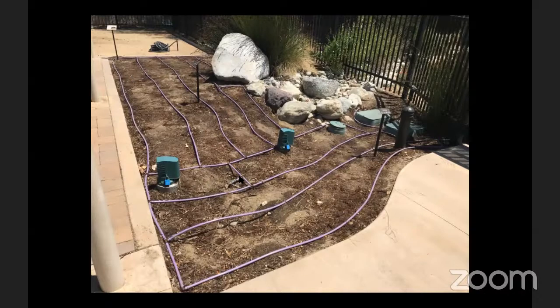And so we could come from 1 point of connection, and using our different fittings, we can basically lay things out. We went in a couple of different directions just based on what was going to be easiest for the layout. And you can see we aimed for it to be roughly 18 inches apart. And so you get, in real landscape, sometimes some narrow areas. Generally, I'll have things be a little bit closer rather than a little farther apart, because I'd rather have it be a little bit moister in one area than too dry. And it all kind of around the edge comes back together. So this is just fine.